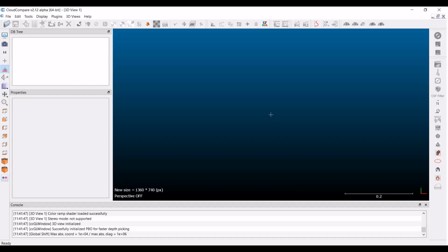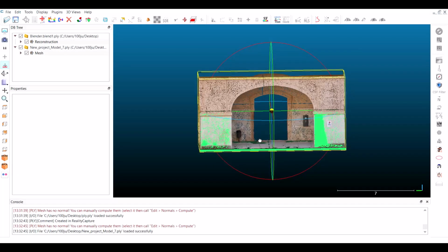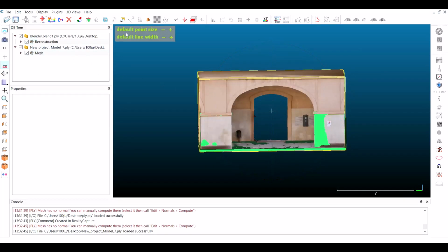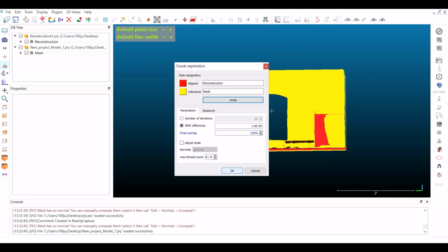Comparison with Cloud Compare. The loss of important information is not always noticeable, so software such as Cloud Compare helps us diagnose our model. We insert the two three-dimensional entities to be compared. In this case, a photogrammetric polygonal mesh and a rock model that simulates the alignment of the pillars.